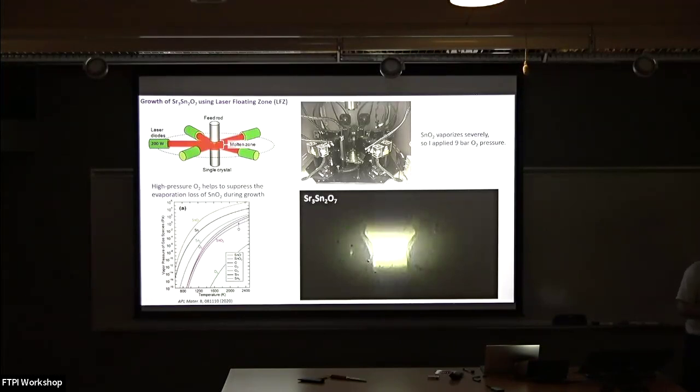How do you prevent the evaporated material from clouding up the tube and preventing you from getting the laser power in? Oh yeah, that's a good point. Outside the growth, we use a quartz tube. Sometimes the material can get attached to the quartz tube, but it suddenly gets vaporized again by the laser. So usually it covers other parts of the quartz tube, but not the part where the laser passes through. Okay.